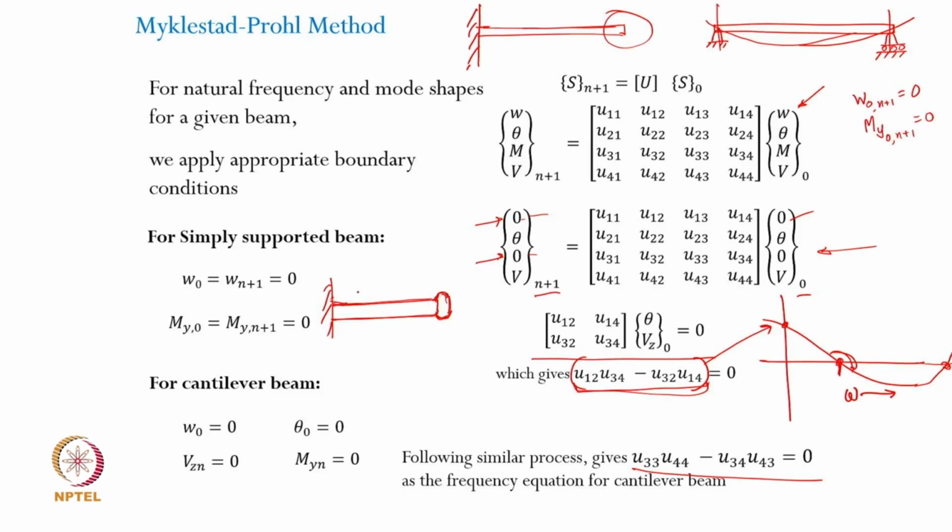Again, this entire process is an approximation anyways, right? So you will be discretizing it, and I can have the last end element to be like this. If this distribution is not regular and it is small in size, but there is enough additional mass there, I can lump the mass of this entire segment into the mass of this particular segment here, okay.